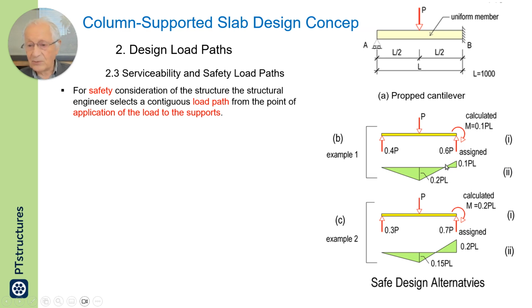Then we draw the bending moment diagram, which is arrived from the loads, and reinforce the structure according to our own bending moment diagram. The moment diagrams will be different. The reinforcement will be different. The load paths are different. Are we limited to these two? No, there can be more.